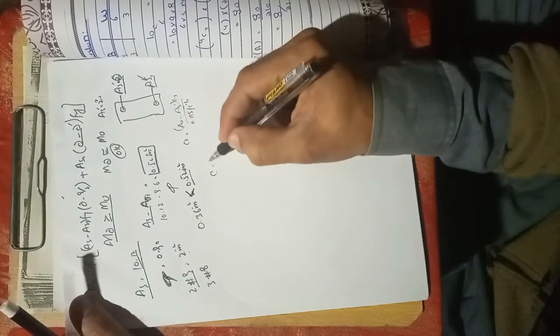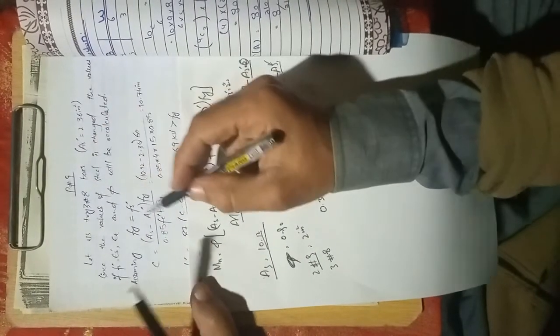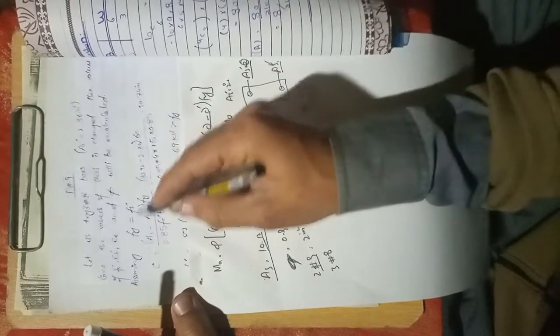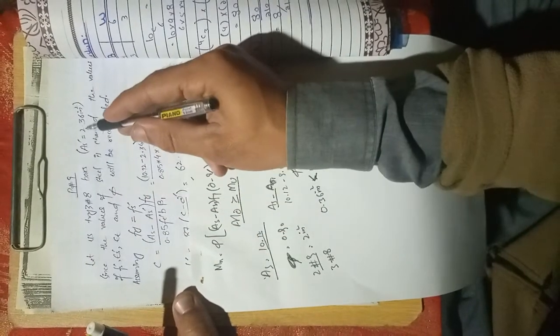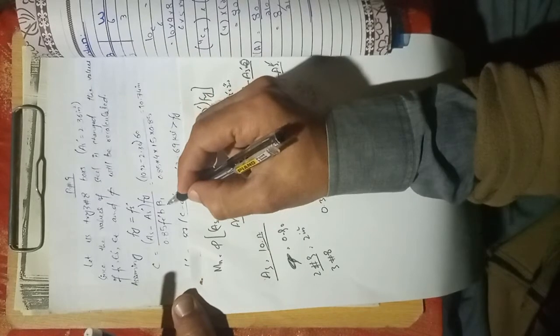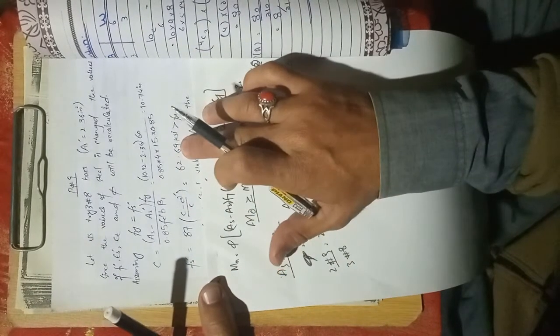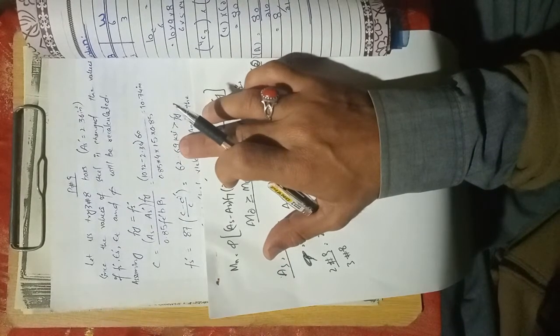So this is the a value, then you calculate the c value, which is a equals beta 1 c, right? So here you see, they just combine, they plug the value of a right here, and we got this final equation. So a is already known, it is now this one, because we changed the bar selection, right? And the b value is the same, beta 1 is the same, c value is now 10.74, fs prime value is recalculated, and here we are lucky that the yielding criteria still exist or still prevail, right?